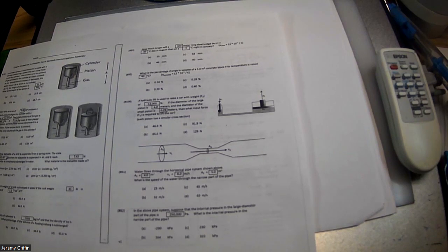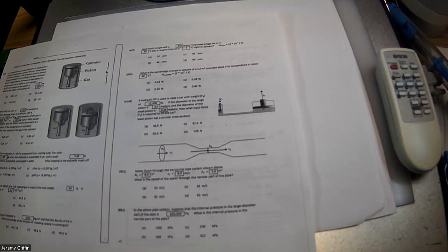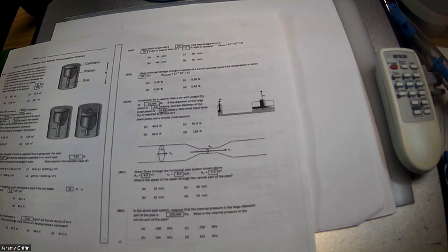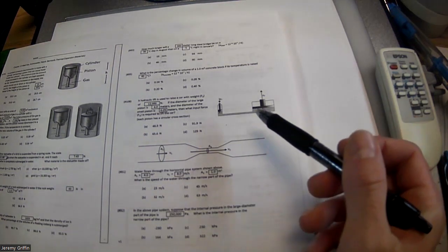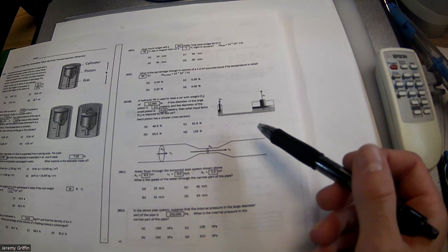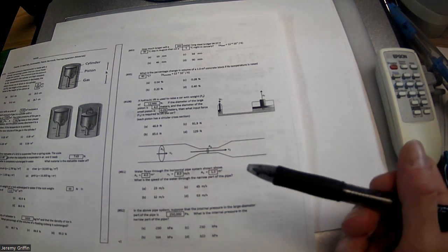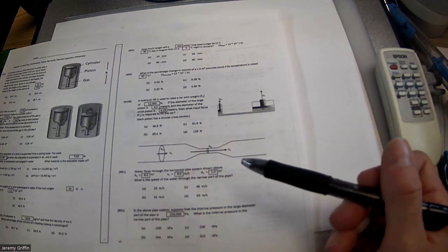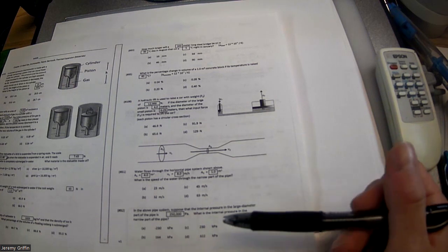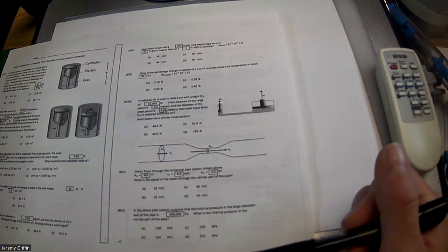You know what this reminds me of? Do you guys remember last semester setting up those pulley systems and getting a mechanical advantage? I still got it set up over there. You guys see that? It's a 5-to-1 mechanical advantage pulley system. So you can lift something 5 times as heavy as your input force. Now, you don't get something for nothing. By increasing your strength, there's a way that you're paying for that. Do you guys remember how you pay for that with the pulley system?